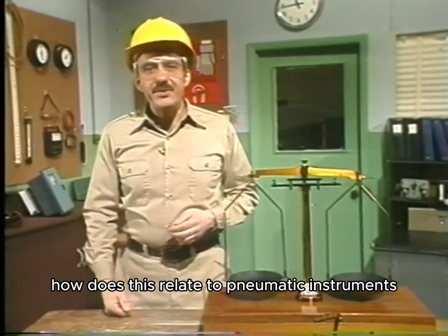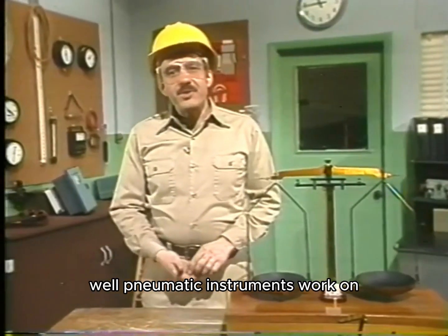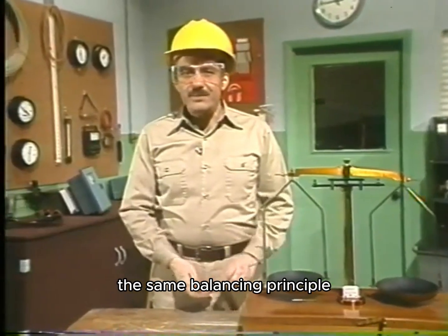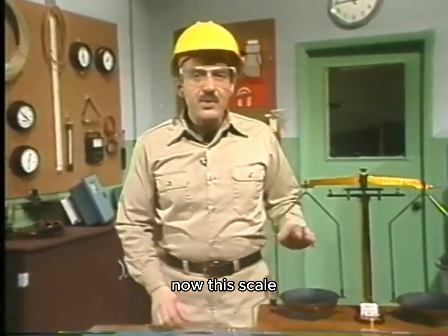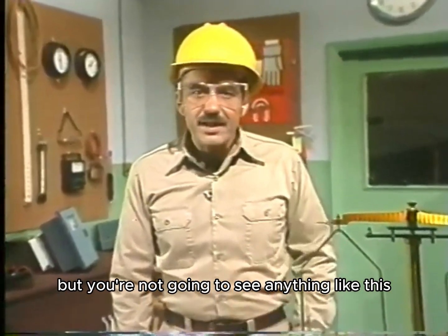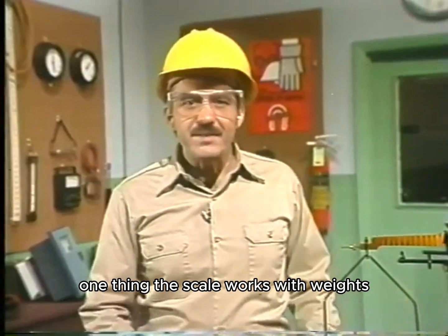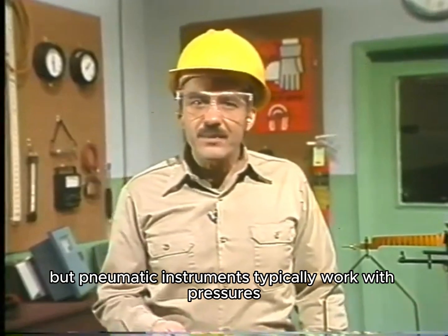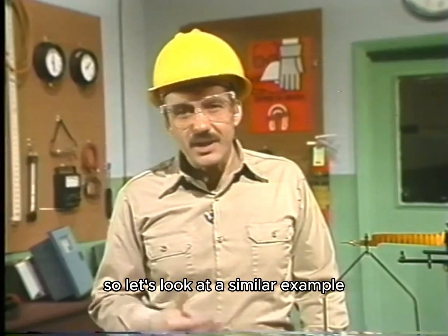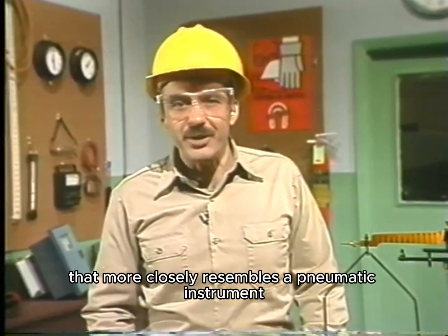Well, now how does this relate to pneumatic instruments? Pneumatic instruments work on the same balancing principle. Now, this scale was pretty useful in describing the balancing concept, but you're not going to see anything like this inside an instrument case. For one thing, the scale works with weights, but pneumatic instruments typically work with pressures. So let's look at a similar example that more closely resembles a pneumatic instrument.